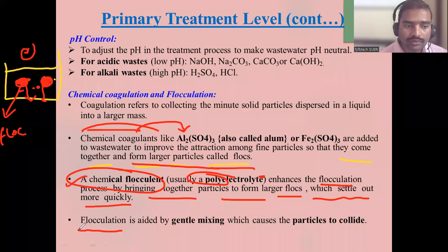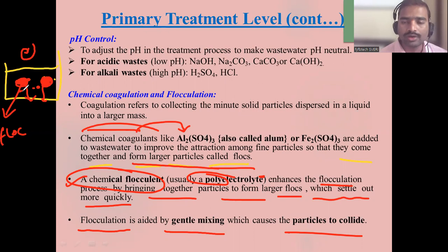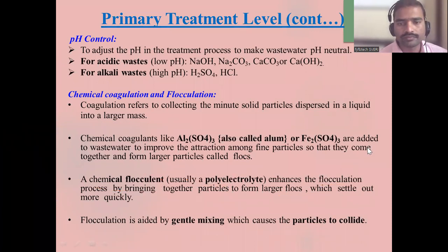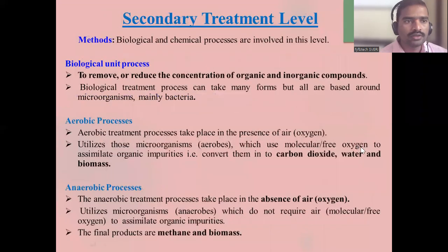Flocculation means a gentle mixing which causes the particles to collide with each other. Whatever particles are there, we have to gently mix them so that one particle mixes with another particle, collides, and becomes a big particle. Is it clear, everyone? Yes, sir. Yes.